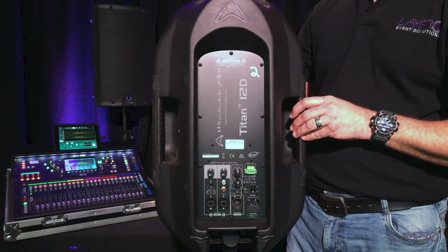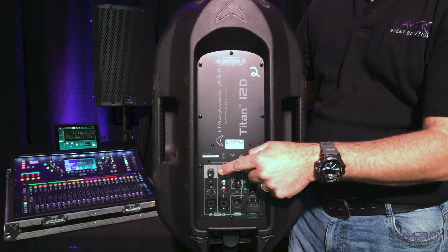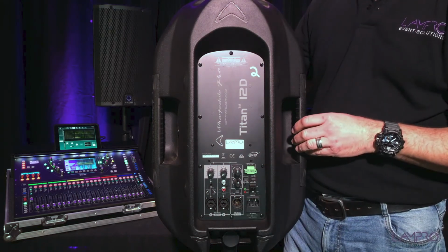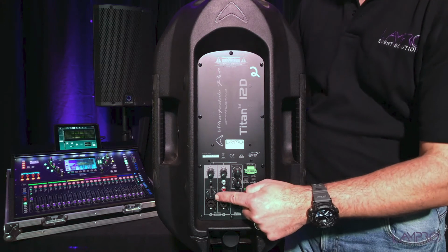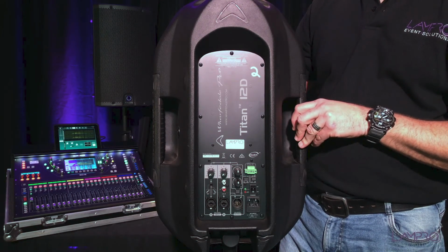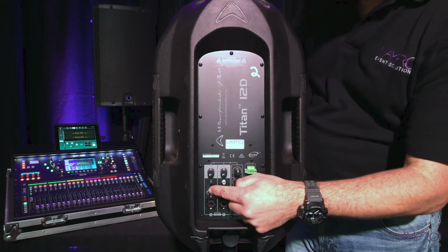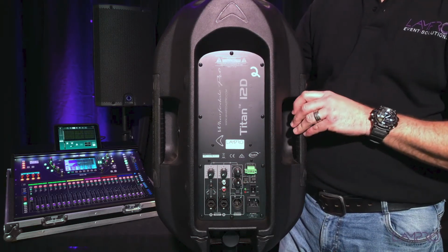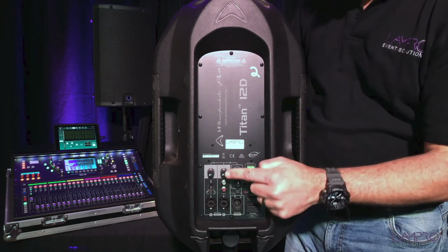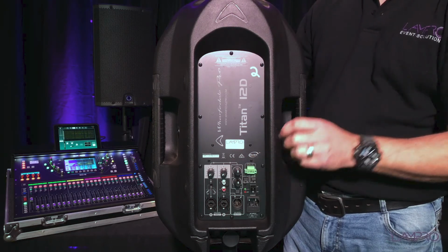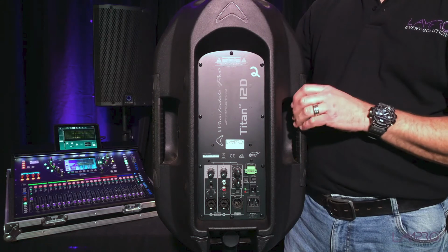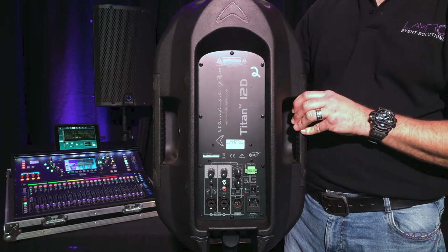If we have a look on the back, you will see a 2-channel mixer with XLR TRS combo inputs at the bottom that can be used in either mic or line mode on channel 1. If you want to use the speaker with a microphone connected directly to it, you simply switch it to mic mode. And to use it with a mixing console, it can be switched to line mode. Or channel 2 can be used as is. Just remember to switch channel 1 back to line mode when using it with a mixer to avoid speaker distortion.